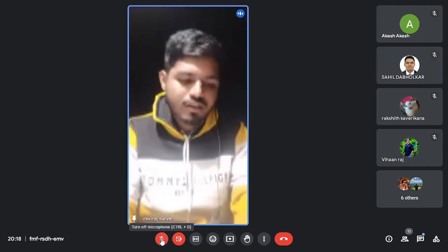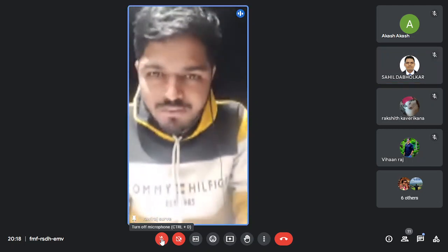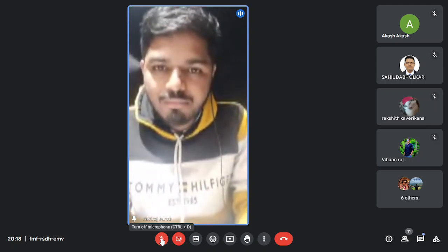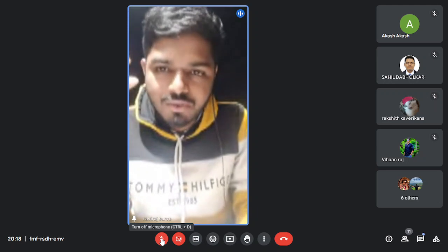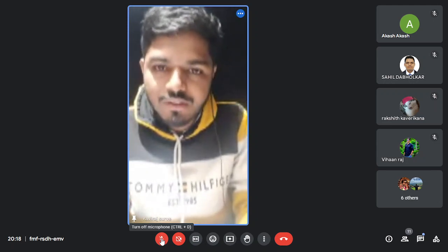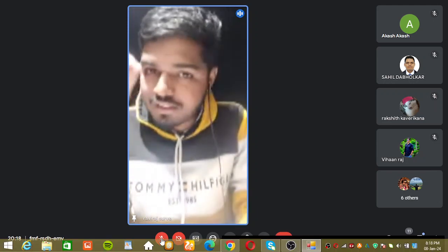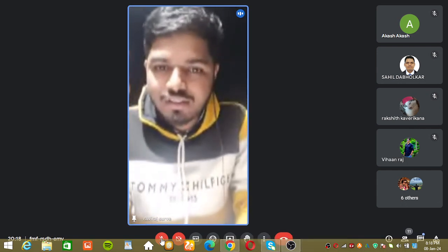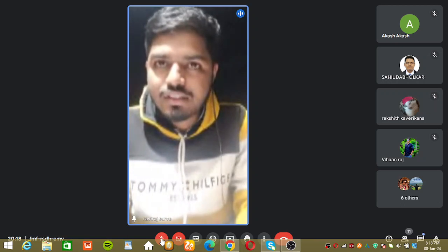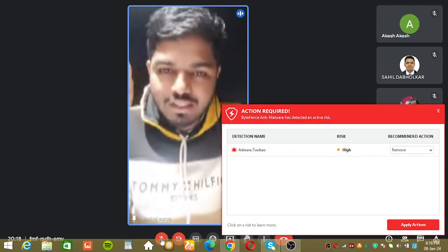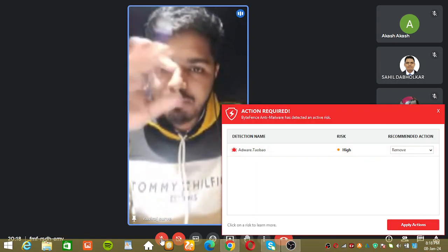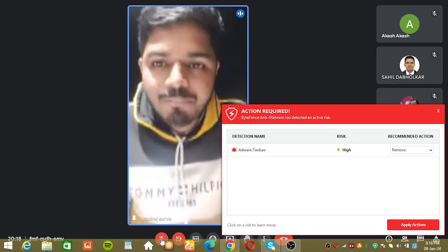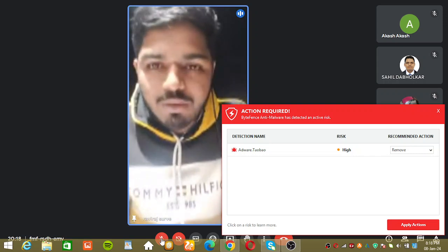Right, because we use a rotary compressor, there are some rotary parts, and for these rotary parts we have to provide lubrication oil. For this lubrication oil, we set the desired pressure. If the pressure decreases below the set pressure, then this safety operates and trips the compressor, and it avoids damage to the compressor. So this is the low lube oil pressure safety.